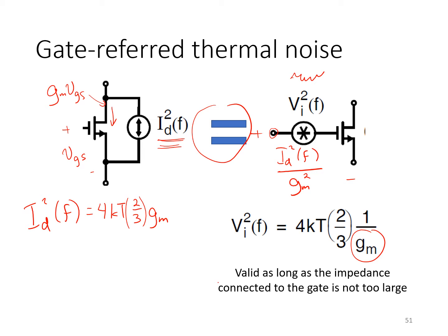It's not going to modulate VGS at all of this transistor, so it's not going to give rise to any change in drain current. So that just illustrates that this equivalence relies on the fact that you would get a proper equivalence if this were small signal grounded. But in other cases where the impedance connected there is large, then it's not a strict equivalence.